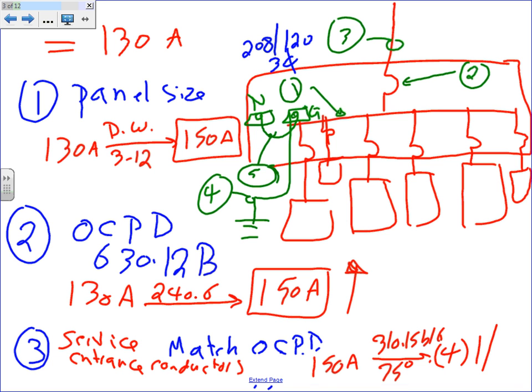Each one of them is number 1 AWG, and they're going to be THHW. Done. I have 4 conductors, number 1 AWG, THHW. Which conduit? PVC schedule 80, if it's service, is a good suggestion. And what's the conduit size that you're going to be using? What's the conduit size for these? If I remember how to use that one.